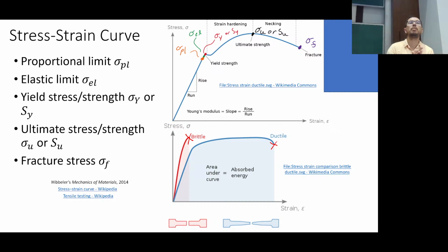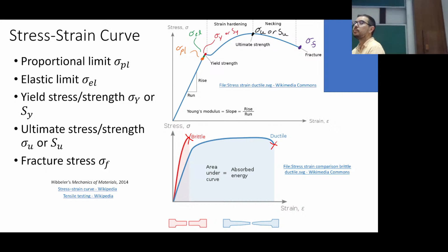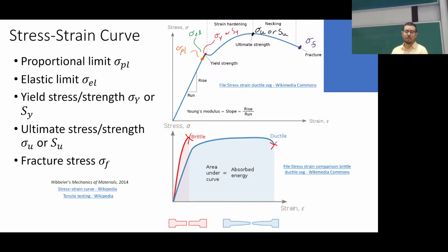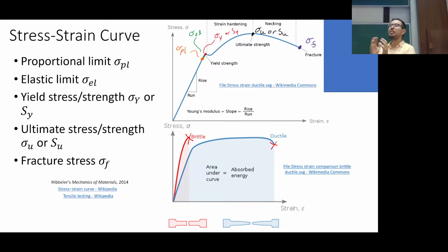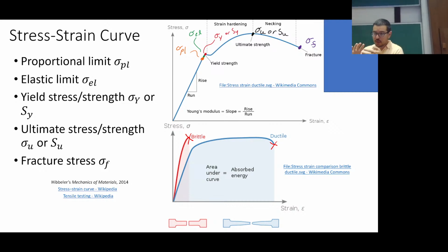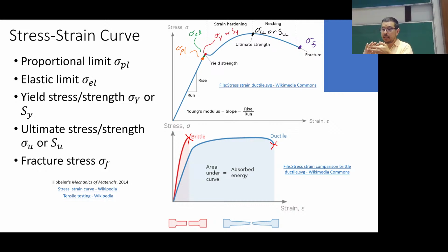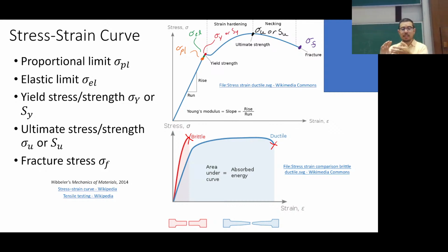Any questions up to this point? Yes? Why is it that just before the fracture, the strain goes down a bit? I will hand wave there and say there are grain boundaries, there's slipping, some sliding at the molecular level. You create these dislocations in some materials, the metal alloys, and then things kind of lock again into this next level.